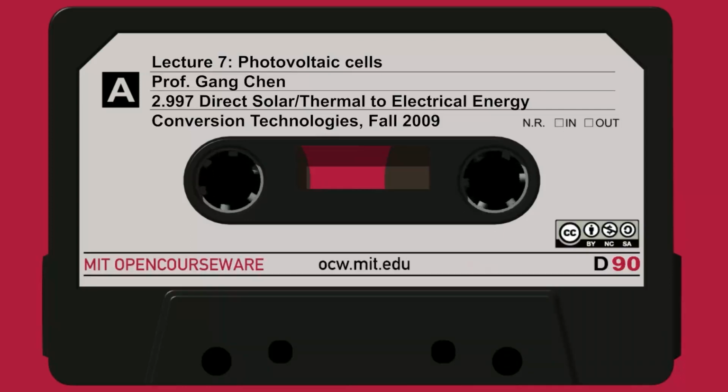Not only do you reduce reflection, once the light gets into the backside, if it's a metal, you reflect it back. You don't want some of the photons to go out, so you trap more light. And the difference between single crystal and multi-crystal is that with single crystal, you can get a regular texture, while multi-crystal does not get a regular texture. It's just a manufacturing process and crystal etching.